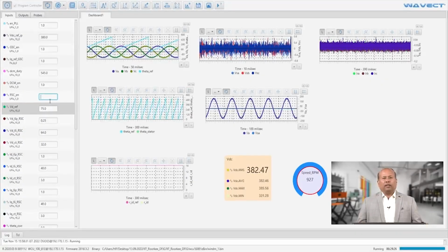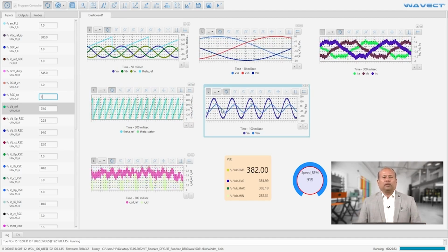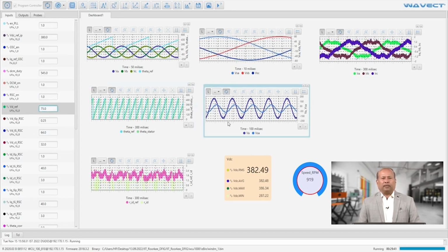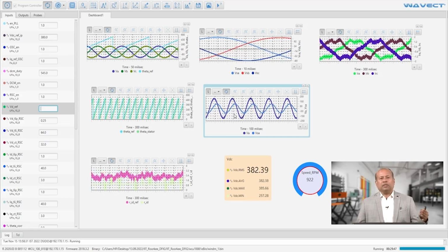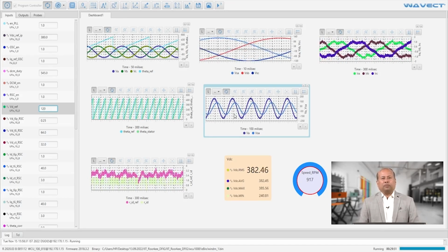Next, we provide the PI value of the rotor side control and enable the control loop. The RSC is first used to build up voltage in the stator side and then match the phase difference of the grid to the stator till they align for the synchronization purpose.